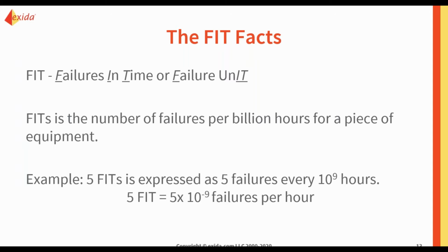These failure rates can be broken up into safe detected, safe undetected, dangerous detected, dangerous undetected, and we will get into all the different types and exactly what they mean in different applications later on. But these failure rates are extremely important pieces of information for the end users.